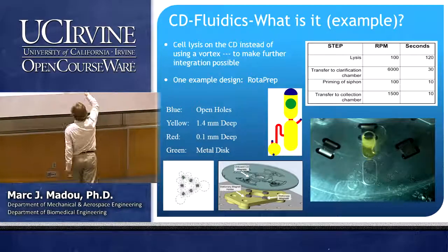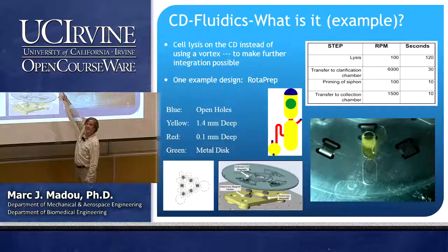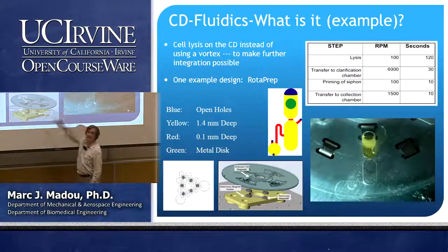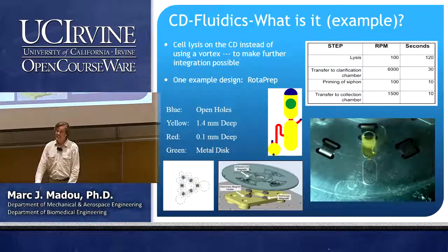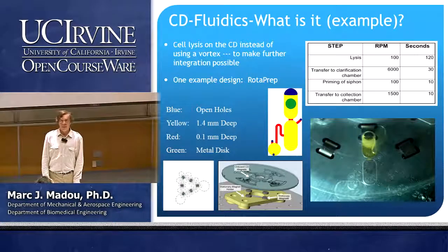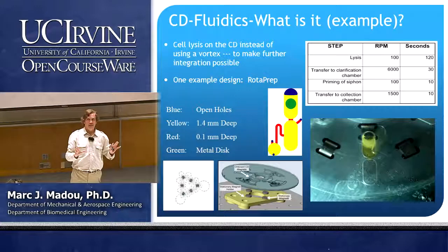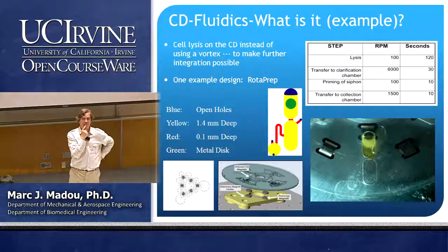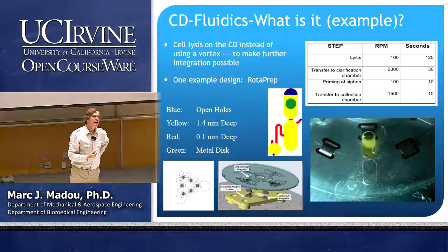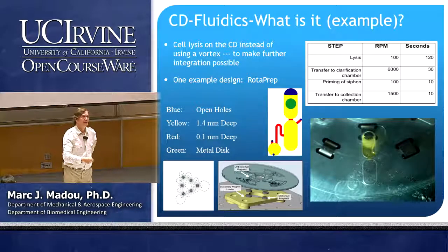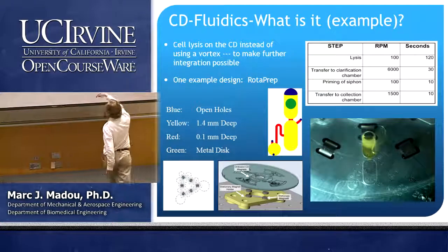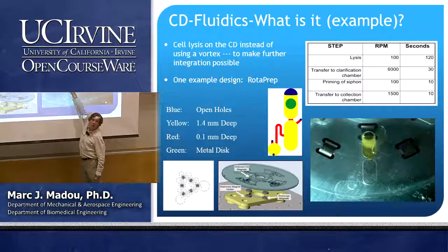Look, while I'm spinning, there's no tendency whatsoever for the liquid to go up into that capillary, although that capillary, and I neglected to say that, is hydrophilic. Polycarbonate is hydrophobic, so that whole disc overall is hydrophobic. But that capillary, I've made it hydrophilic. So the liquid would want to go there if it only could. How can I make it go up there? By reducing the RPM. Because if I go back to lower spinning rates, the centripetal force pushing on the liquid is less, and now it can go up there.